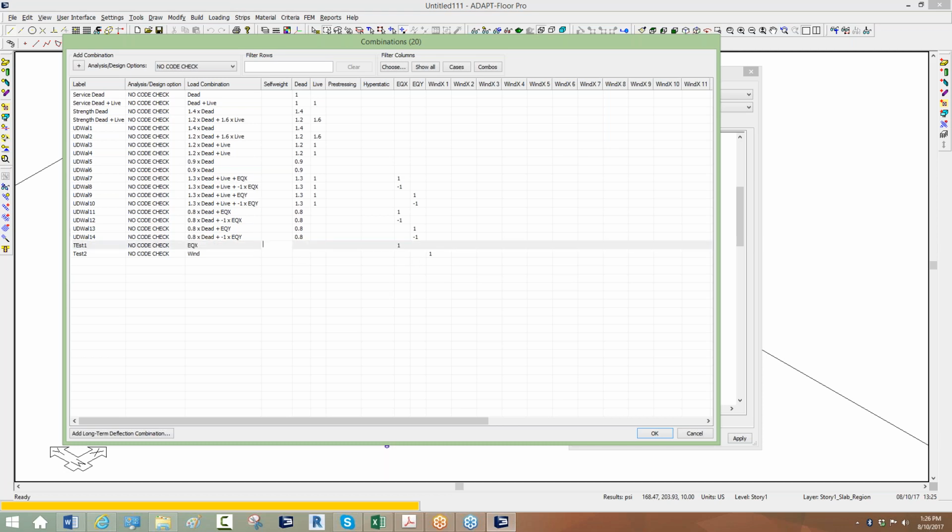And I could apply factors to my gravity loads. Self-weight, that's native to Builder. We're automatically calculating the self-weight of the structure just based on its geometry and volume. The dead and live loads, those are externally applied loads in Builder, but they stem from the import from Etabs. So we're only going to produce a result for these 2 lateral loads independent of any gravity load.